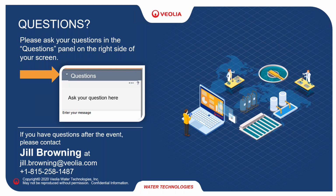The system is designed for, I do apologize for Americans, 26,000 cubic meters per day, which, doing a quick math, is probably a bit less than 5,000 USGPM. Mind you, that's the hydraulic capacity. The system is normally operating at half to 2/3 of that value. Residence time in the reactors is on the order of 30 minutes in the first and a little bit over an hour in the second reactor, but obviously that depends on the flow rate, so low flow rate will be higher, high flow rate it will be lower.